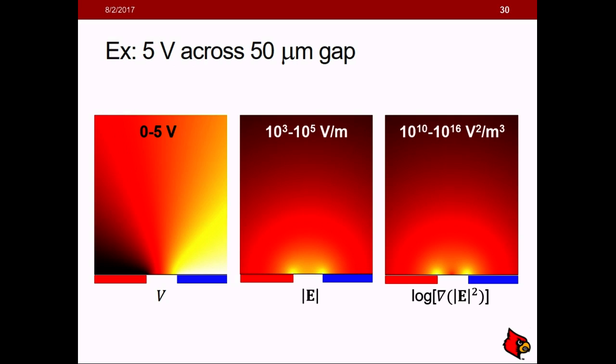So if you have a particle out in the bulk versus a particle that is here, this one is likely not going to be manipulated, or it's not going to be manipulated as strongly as that near the electrodes, because the field strength is just weak out there. So for example, just to put some numbers to this, let's say you have 10 micrometer particles.